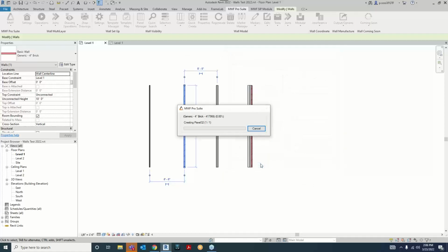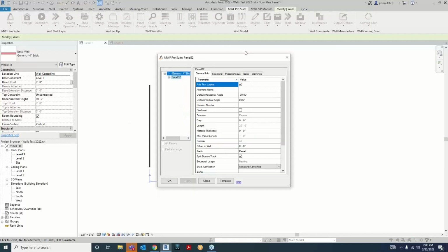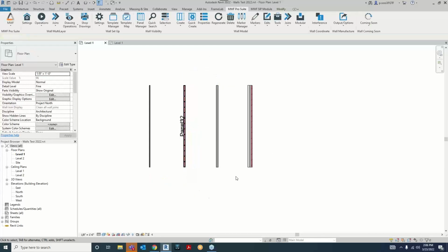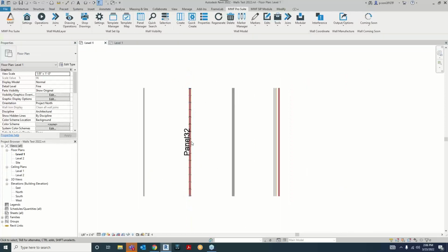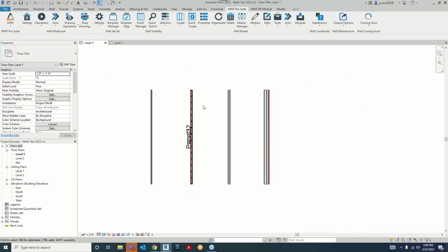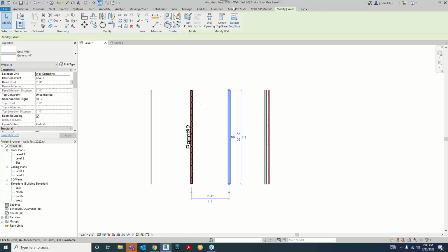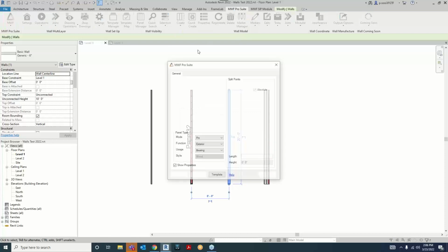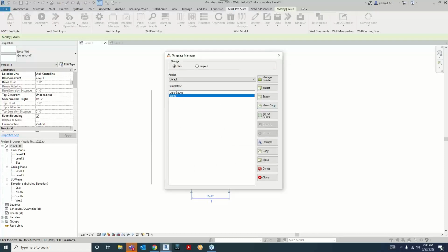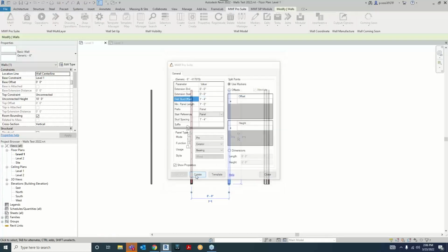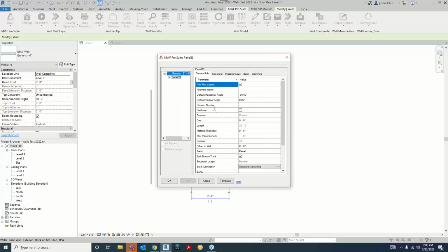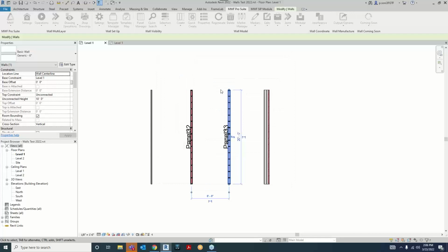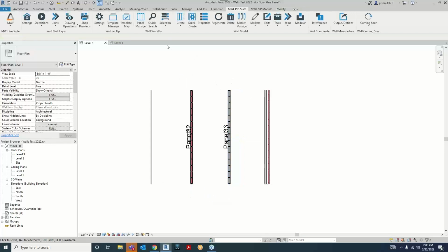and all you need to do is just hit create and just hit OK. And this will be the manual way to create the panel. It will create a panel, it will label it. So this is how you can literally repeat the same process: template set as active, close, and create for any other wall. Unless the template is selected, it would not create the wall.